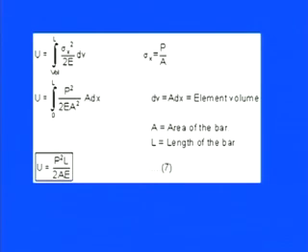If you look at this point, you will find that two or three parameters are really important to calculate the strain energy. One is the material property. What exactly the material is that you are using, because whatever the load application is, if the material is more stiff or less stiff, the deformation accordingly varies, and the elastic strain energy stored varies. The second property is the area, that is, the dimensional part, meaning the cross sectional area.